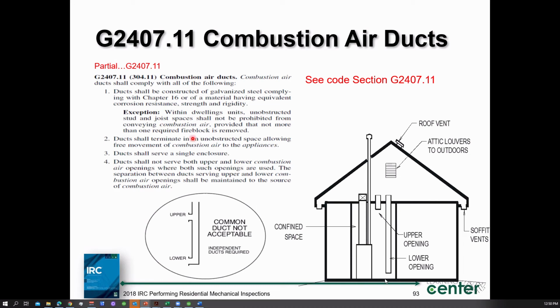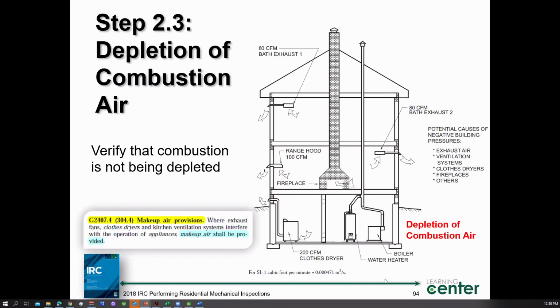If we use this, you have to be careful because it may conflict with the energy code if you're in an exterior wall. You don't want to use this in an exterior wall, because now all of a sudden you don't have any insulation in the stud cavity. Not a good thing. So maybe in other areas in the house, you may be able to pull down from certain areas.